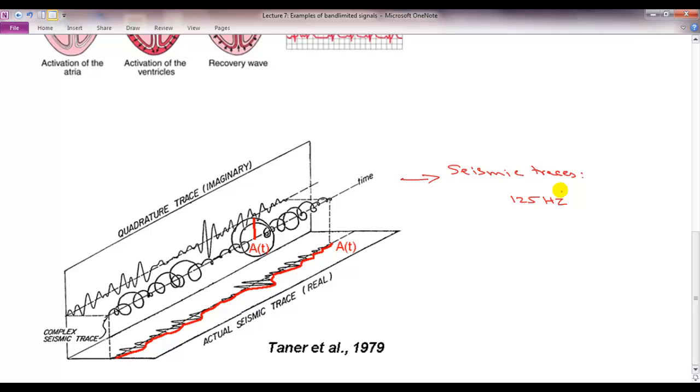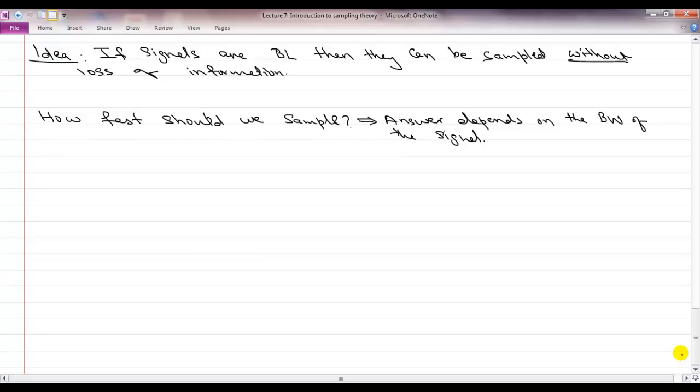That requires engineering understanding or talking to people who do applications and saying, based upon my analysis, it seems that a model for this signal to be band limited up to this frequency is the right model. So we are going to work with band limited signals, but the idea is that the bandwidth of a signal can be 10 kilohertz, 100 kilohertz, a megahertz, a gigahertz, and you have to select your capital T appropriately so that you don't lose information.